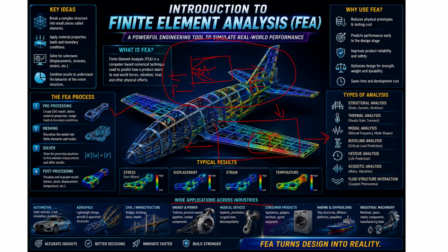The stresses will generate over this region, and as we go away from the hole, the stresses will dissipate. There will be no more stresses at the end of this plate, over here and over here. So we have to check how the stress is going to be dissipated. These kinds of calculations we need to do in FEA.